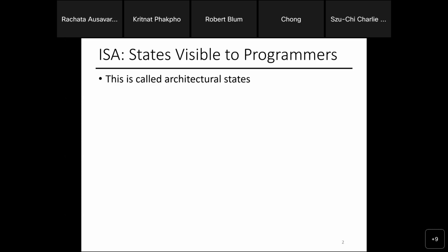Send the signal, hey, stop running at this line. How do I tell what line to pause? I mark it, and that marker is tagged with the address of that instruction. So what reads that instruction? The program counter. If the program counter happens to go to that instruction, I can pause.